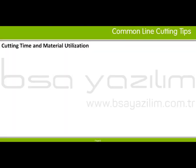The reason for using common line cutting is that it can reduce the time taken to cut the nest and reduce the consumption of energy and consumables by the machine tool. So in Radan nest parts that have the common cutting property, the nester tries to produce as much common cutting as it can. In other words, the nester tries to minimize the total length of cuts needed to cut the parts from the sheet, and so minimize the cutting time of the nest.